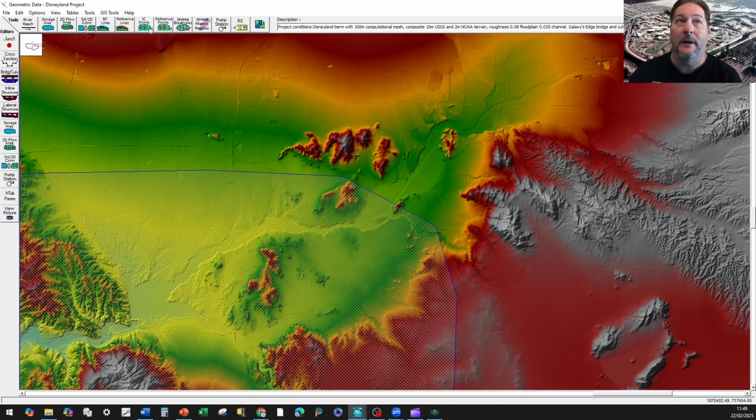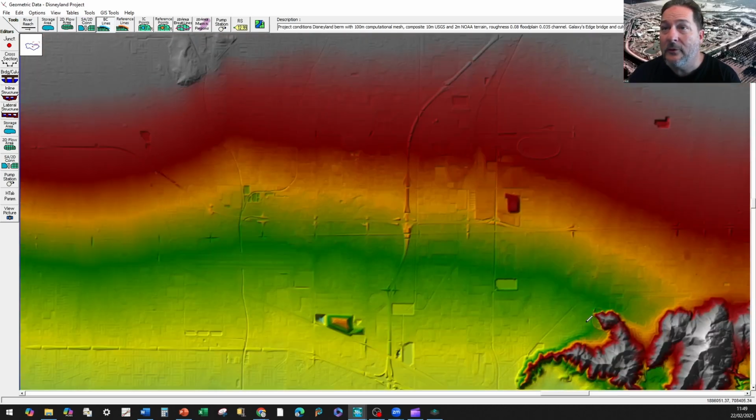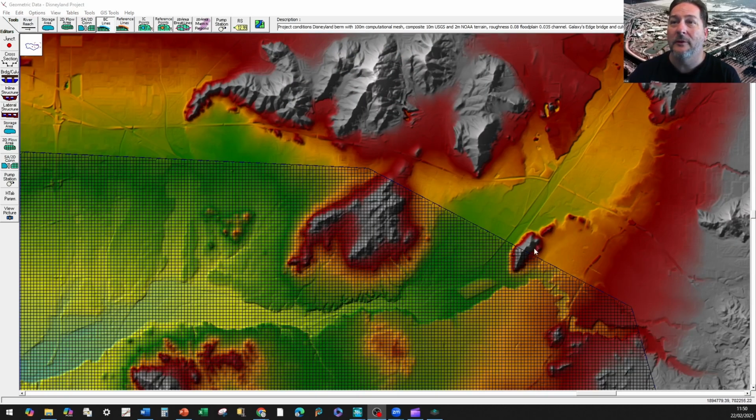So if I'm going to bring inflow into this along a BC line, I'll click on that one right now. Let me just zoom in here a bit, and we'll just draw a cross section where we're essentially going to be perforating this impervious perimeter around the outside. Sometimes your draw tool will disappear and you have to click on this again. I'm going to delineate here from left to right looking downstream. So I'm going to start up here on this hill and move over to this one, double click out there.